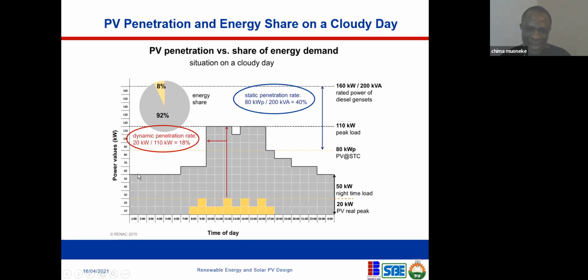You can notice that at any point in time, you're consuming 50, and that's what base load means. So if you have a solar system that is within this range, then you don't have a problem. I think I said this yesterday. But if your solar system begins to exceed your base load, especially during the afternoon, then you need a controller. So this is what base load means.